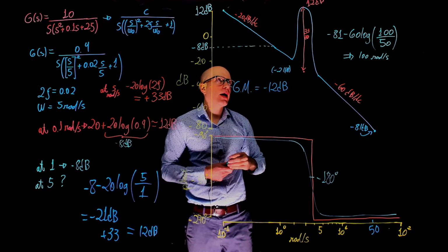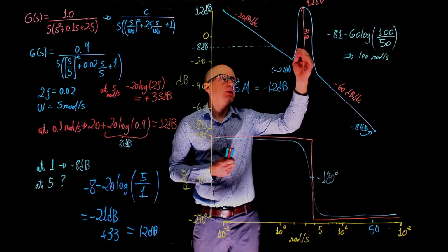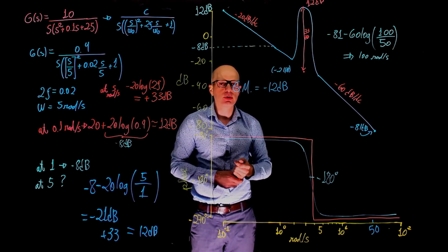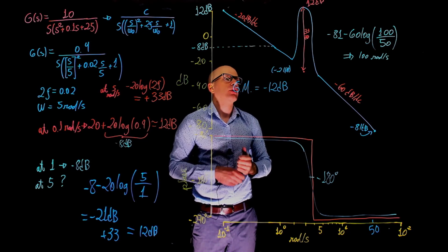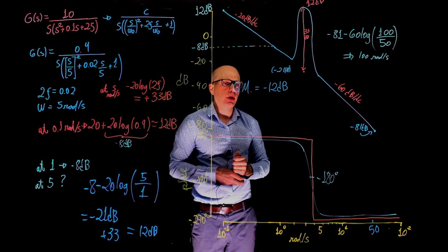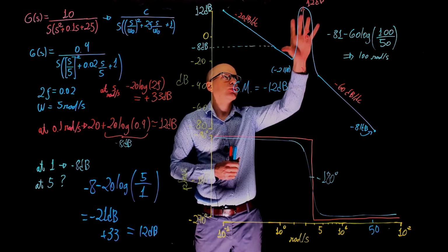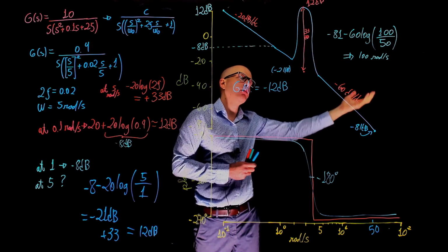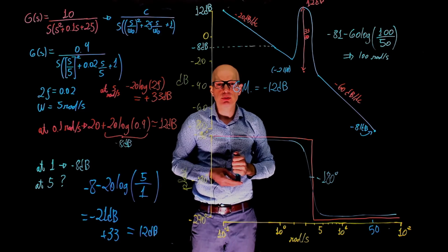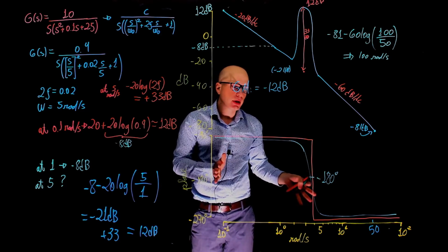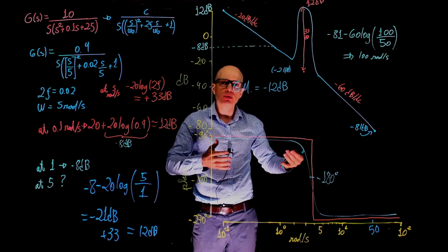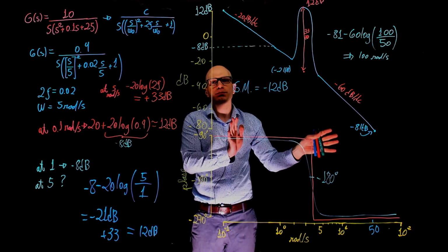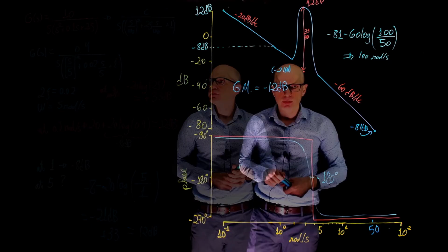This means that, again, we need to add negative 12 dB to make the combination of negative 180 degrees and 0 decibels on the Bode plot. So this will now shift down by 12 dB, and when that happens, past that point, the system becomes closed loop stable. As it stands right now, if this system was to be used in a unit feedback loop with a gain K, this would be unstable.